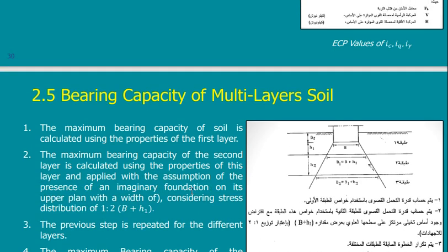So if I do this, then I have a footing. I can just get the dimensions, the parameters and everything, and use the equation. I will get a bearing capacity for the soil. Is this enough? No, it's not enough. Why? Because the bearing capacity of the soil is for a soil of C and phi and special parameters.